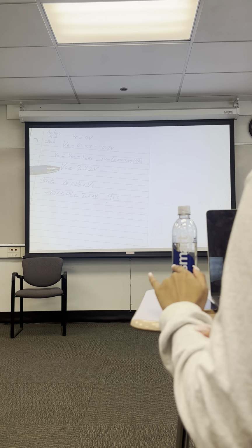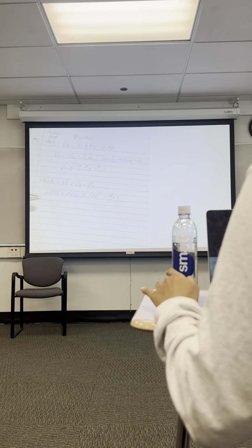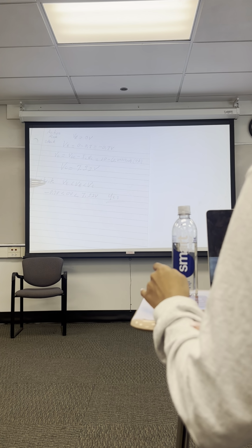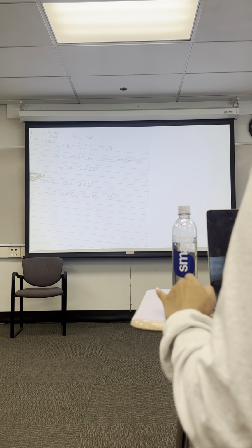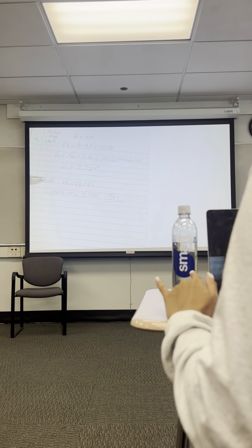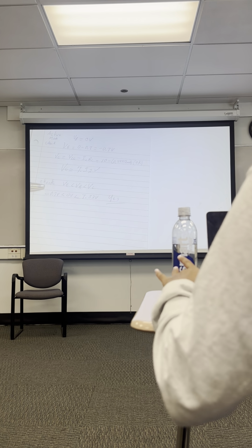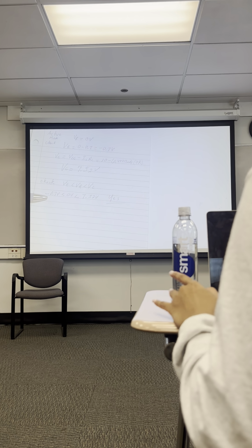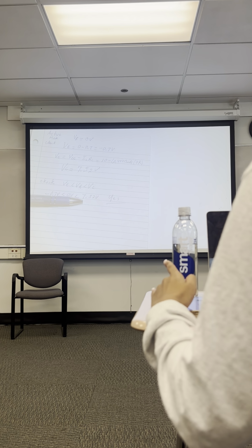The collector voltage is 7.32 volts. And now we check the initial assumption: V sub E less than V sub B less than V sub C. This is important in the write-up for the conclusion of this part of the problem. Now we're checking the numbers, and it's minus 0.7 less than 0 volts, less than 7.32 volts, and that's yes.